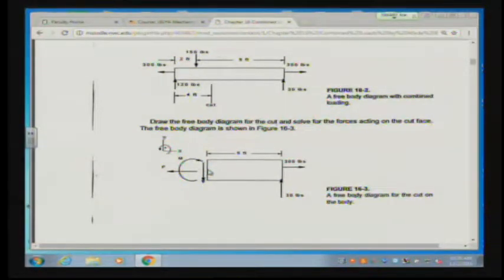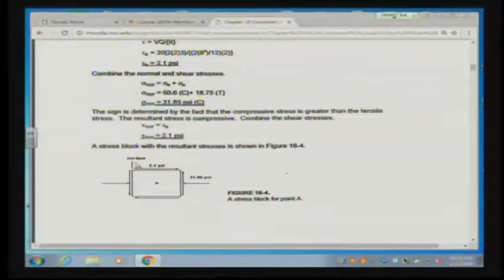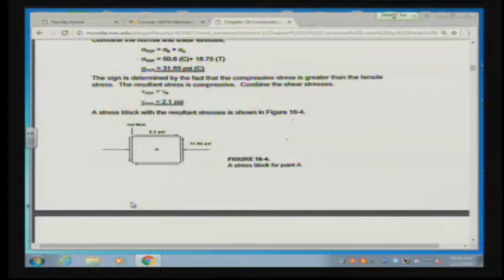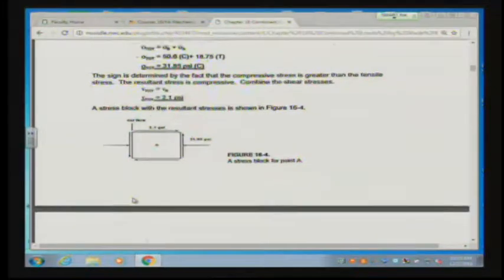You think about the cut face as being the very edge of this item, and then the rest of it goes back into the beam just a tiny little bit. And you'll notice that here the cut face is on the left, and here the cut face is also on the left. Now if I'd cut it the opposite way, I could put my cut face over here, and I would see that it was up instead of down, which just makes sense because it's not really going anywhere. It's just a reaction, and it depends on which lamina you look at, on one side or the other. The direction changes because it is actually overall equal to 0. It's because it's not moving.